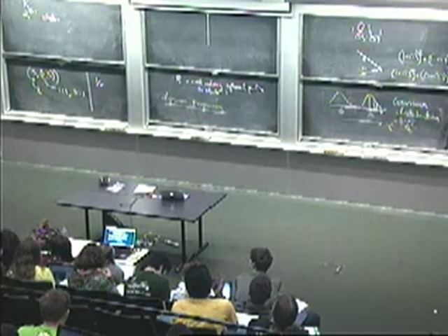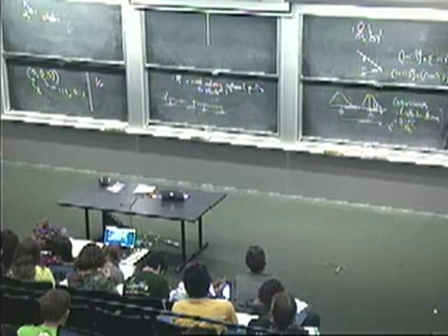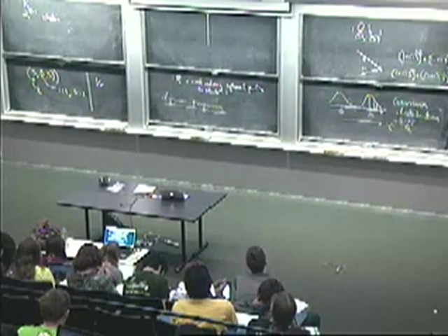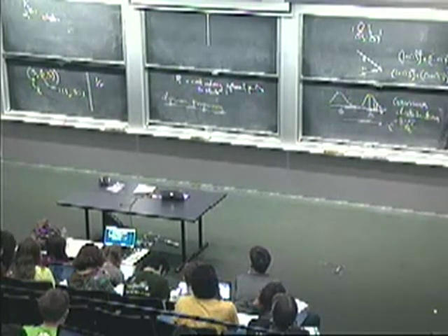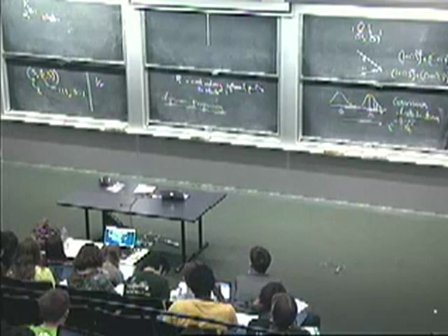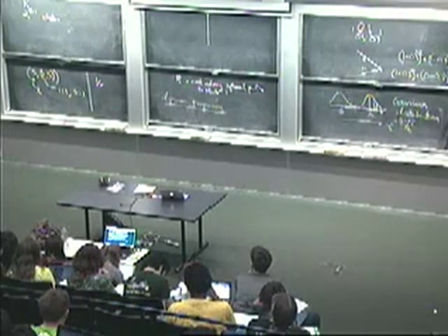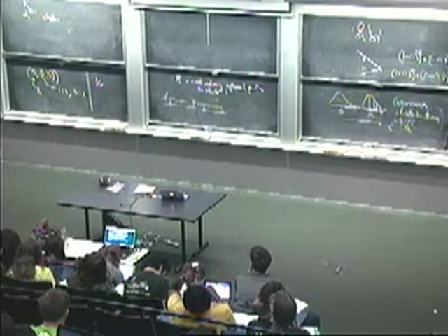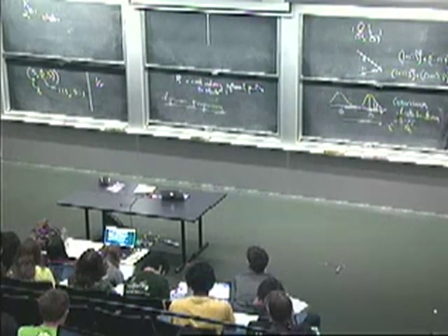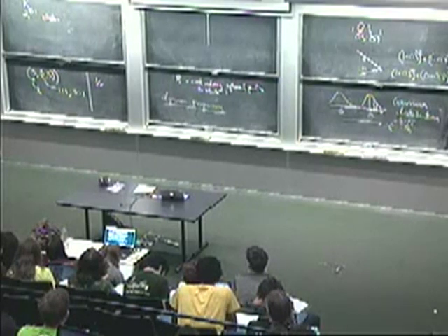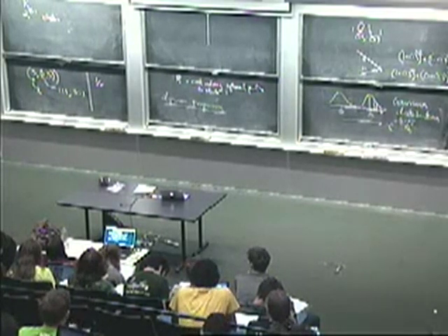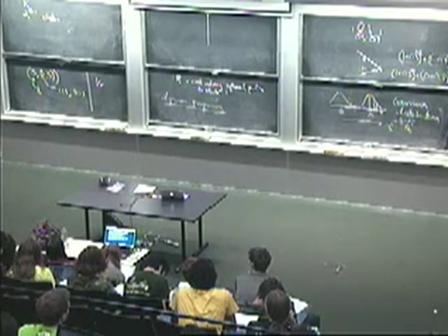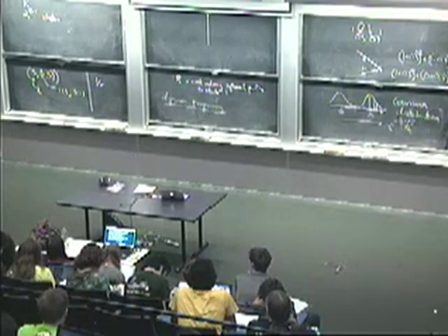This is constraint length 4, and you can actually write out what that would be there. How big is the trellis for the constraint length 4 case? How many states? This last one down there. 8, right? Constraint length 4 means k equals 4, 2 to the k minus 1, so 2 cubed states. So it's 8 states that we're talking about.